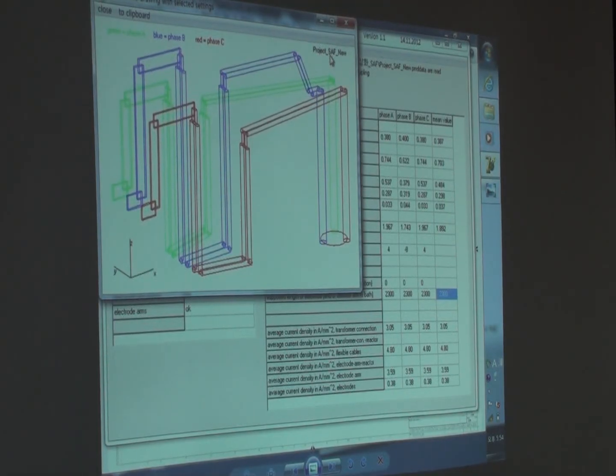You can also use this kind of construction for making steel from iron ore. We say this is direct reduction. They made attempts in Germany, a direct reduction of iron ore with this construction, but it was too expensive using electric energy, and therefore they use gas energy for reduction.